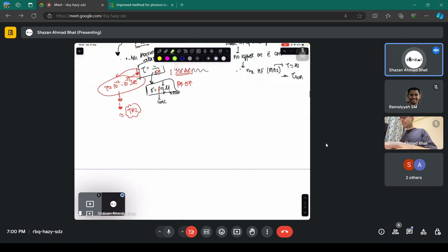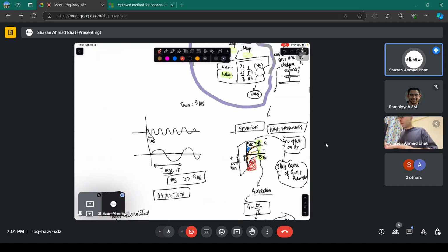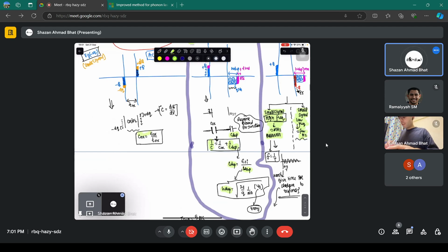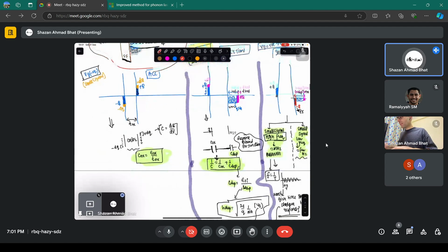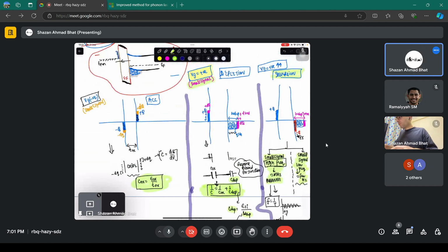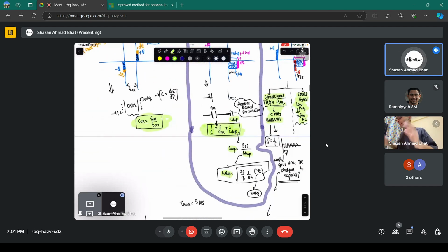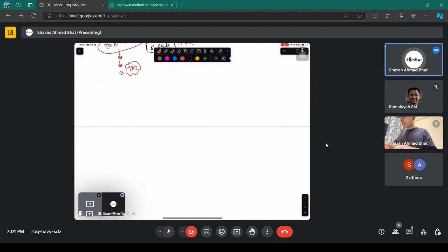What happens when we draw this capacitance versus voltage? Now you have everything. You have the oxide capacitance, you have the overall capacitance in the depletion region, and then you have the inversion capacitance, which depends upon two modes, whether the small signal applied is high frequency or low frequency. And that's going to reflect in the capacitance versus voltage curve. Let's say this is capacitance here, this is voltage, and note this is the gate voltage.